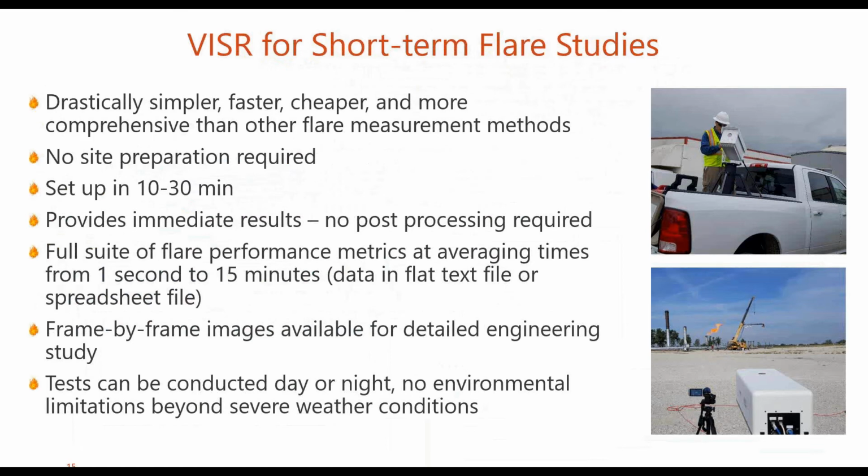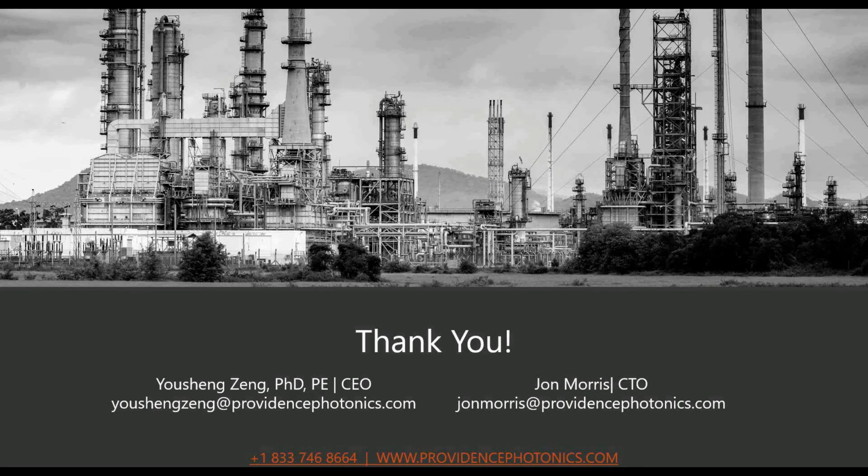And if needed, we can capture short clips of 30 hertz raw data. If you're a combustion engineer and you really need to understand what's going on in the combustion zone, we can study the spectral data at a very high temporal resolution. It can be a very good diagnostic tool for a problem flare, or just to really understand the evolution of the combustion of a particular flare. So that is an introduction to VISR and the Mantis device, which is built around the VISR method.